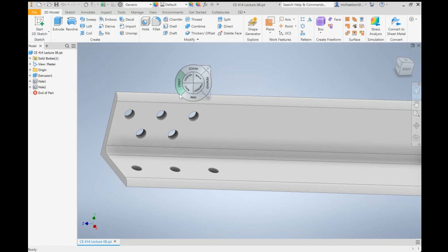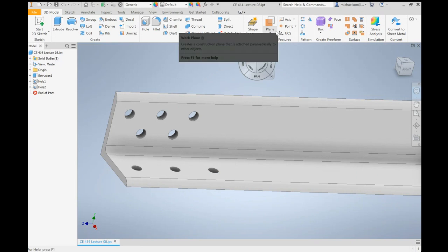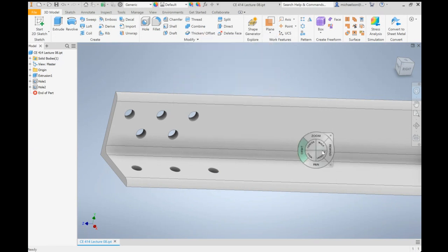Now, if I had just drawn a single path like that, sure, this bolt is on the lead line, but if I were to fail that path and yank the member, not only am I separating the member, but I have to shear these two bolts in front, and that would violate the rules we've established. So all the failure paths are going to be the ones that follow this lead line and leave the bolts intact. For this connection, that was really only two paths.